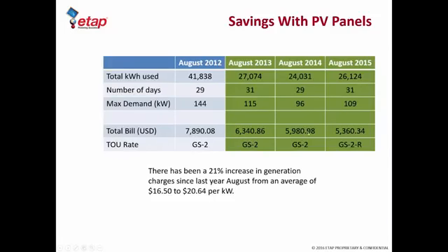And this was done by us negotiating with the local utility, and that's something, again, that is part of the lessons learned, to make sure that you're on the correct schedule. We switched our time of use rate. We switched over from GS2 to GS2R, which is a general schedule rate for renewables, which was offered again in 2015. So that essentially lowered the time of use and demand charge. So again, reduce the overall bill.